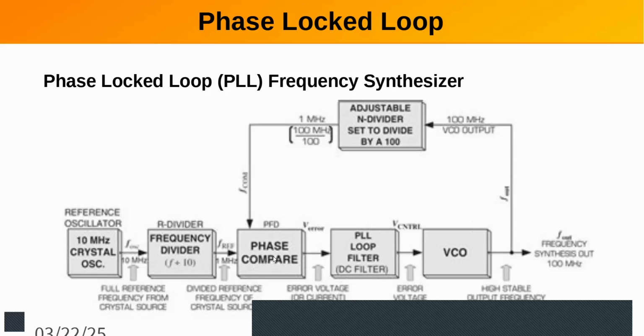When the output of the phase comparator is essentially at zero, and you filter out all the high frequency stuff, so you just integrate that, you use that as the error signal to drive the VCO.